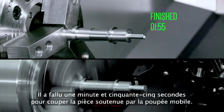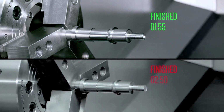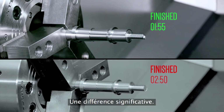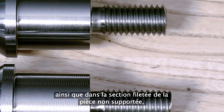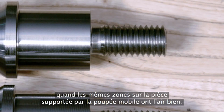It took 1 minute and 55 seconds to cut the tailstock supported part, and 2 minutes 50 seconds to cut it without a support, a significant difference. And we can also see visually there is significant chatter on the front journal as well as in the threaded section of the unsupported part, whereas the same areas on the tailstock supported part look good.